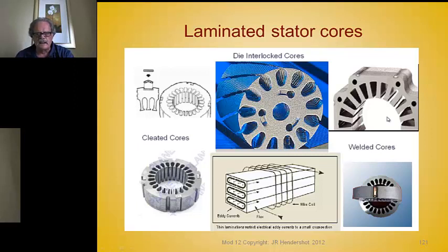But here's some examples of welded. This is a very poor welded core that has filler metal added. It takes up, it's way too big. It's going to cause eddy currents in there. It's a poor weld. Here's a very excellent weld. Very tiny, small welds. That's desirable.